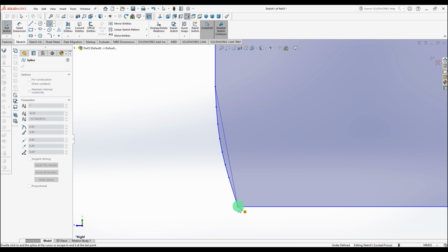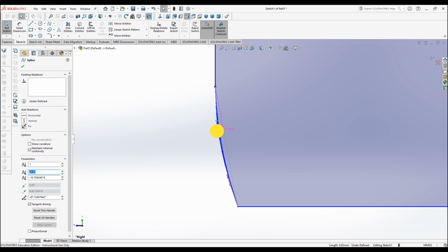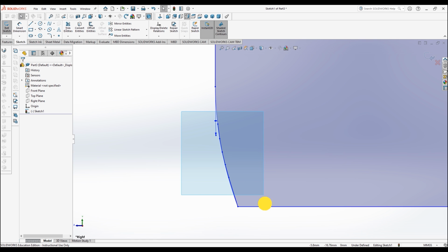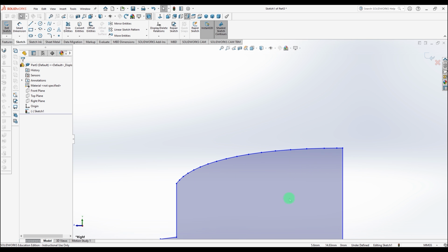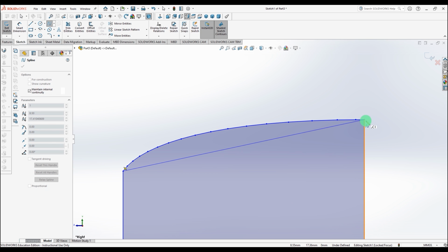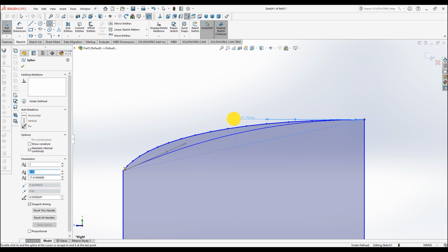Now I mentioned previously that the splines in my 2D CAD software are fine, but when they bring into Solidworks it brings them in as a series of short, straight lines, like a faceted curve. And that's fine. Geometrically they're okay. The thing would print all right, but when I make this 3D, it will look like it's got these sort of threepenny bit facets on. So I always redraw my splines in Solidworks. I would do the same if I'm working in Fusion too, although I prefer using Solidworks. Perhaps we ought to do this in Fusion at some point.